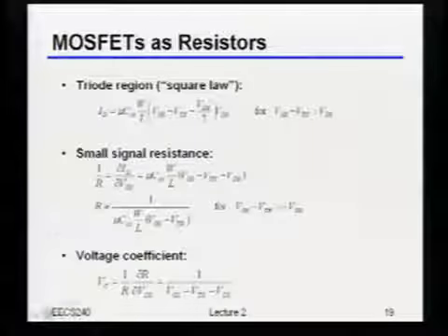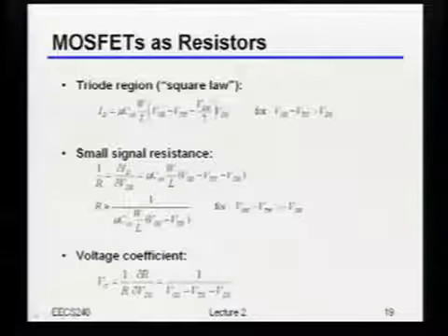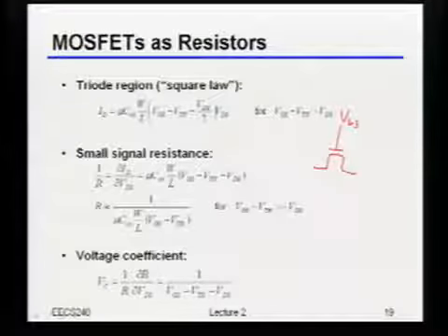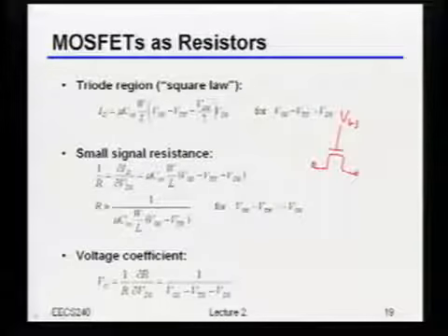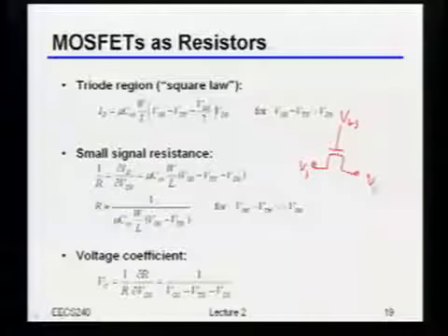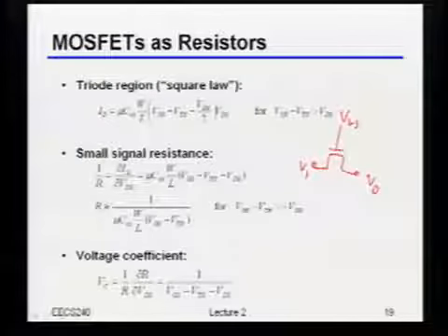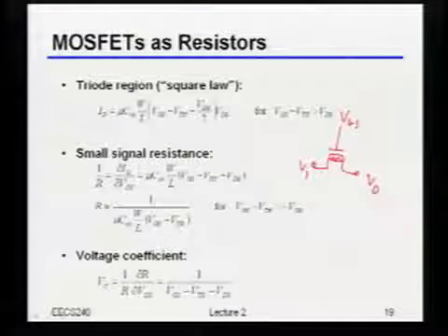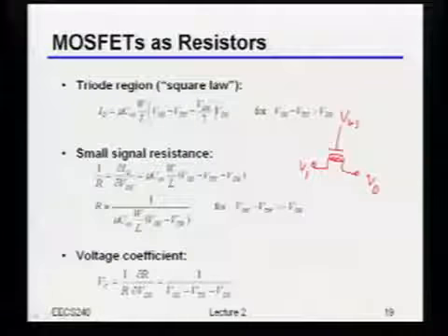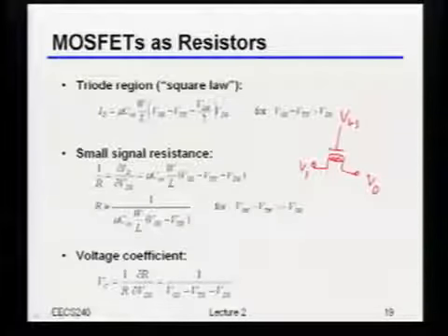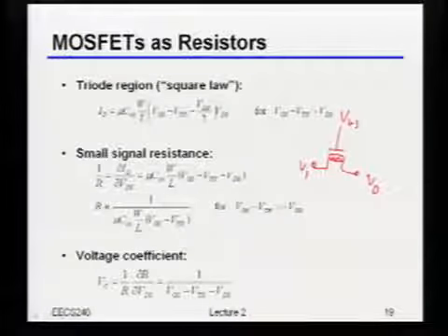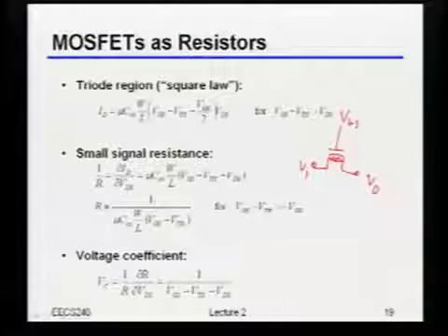The way you do that, in case it's not obvious, is basically just put a relatively high VGS on the device so that you make sure it always operates in the linear region. If it's deeply in the linear region, then the channel charge is relatively flat, and you can pretty quickly work out the incremental or effective resistance that you get from that. I wrote out a few of the equations over here. They're not super critical. I think you guys can figure them out on your own pretty quickly.